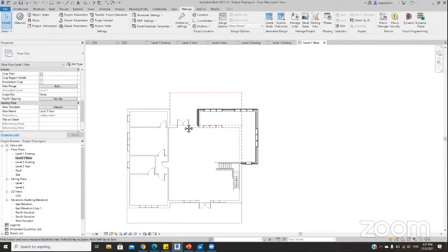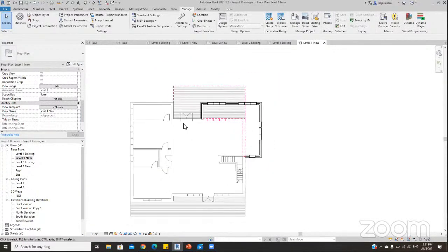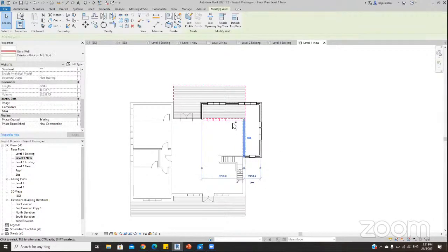Okay. So again, let's say I want to undemolish this element that I have already demolished. What you can do is just click those elements that you don't want demolished. Let's say I don't want to demolish this wall after I have already demolished it, because I made some adjustment to my design. You click those elements and, under the phase created, you ensure that they are under the existing. So we can just see them again inside the existing.